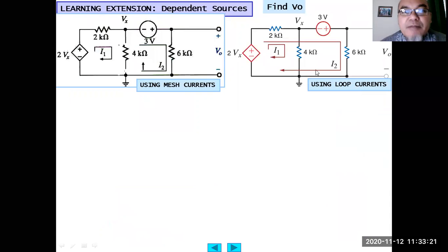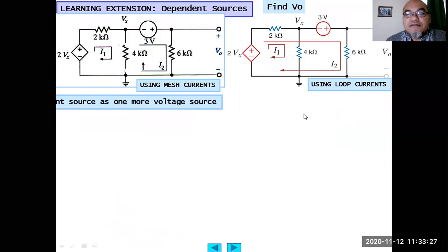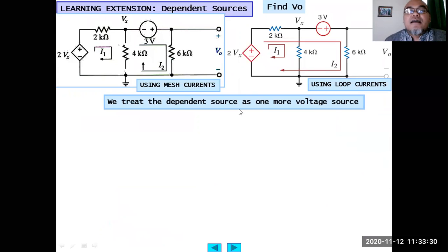Then this is an example of current with dependent sources. I think we have discussed this yesterday, and we can choose either of these two ways. The first one is using mesh currents: loops which do not intersect each other, do not engulf each other. While the second one, you use loop currents instead. So the first one is I1 on the first mesh, basically. The I2 loop current engulfs or encloses the first loop current in this method.